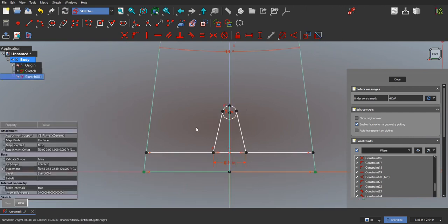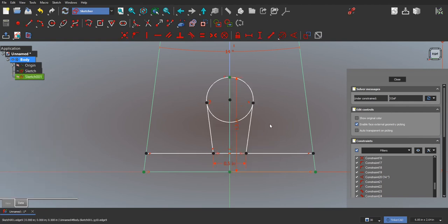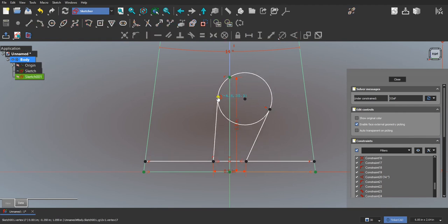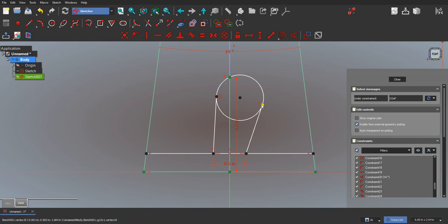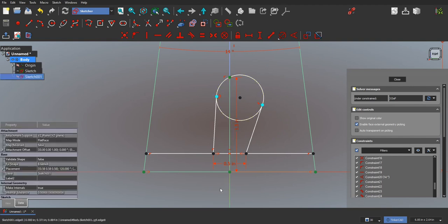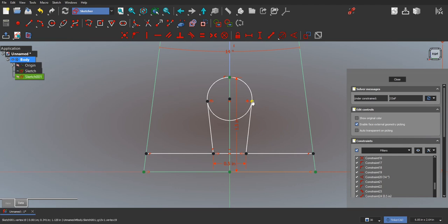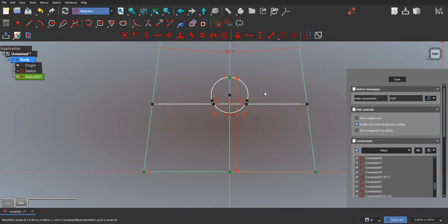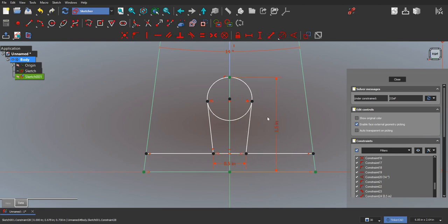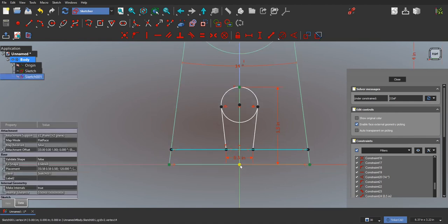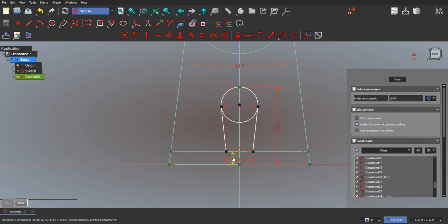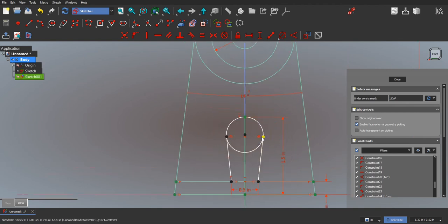And then this line, we know that distance should be 1.5. That's totally not what we wanted. So let's make that smaller. Something's not happy. I didn't make these two lines symmetric, so let me do that. And that should help us out a bit. Let me just undo this. It's freaking out a little bit, but it's sort of my fault. So let me just keep adding these dimensions so fewer things can move. So I think that is the last one we need to define.